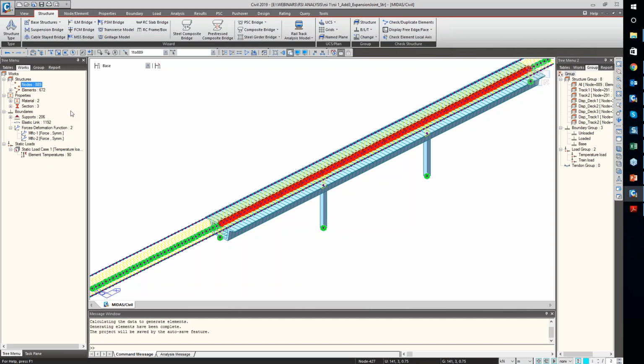Whatever design forces we are getting, we take an allowance of 5 to 10%, and we design the bridge, and then we check it for rail structure interaction. Because you can see here, we need everything about the bridge. We need the pier sections, we need the deck arrangement, and everything finalized, and on that we do this rail structure interaction check. So these derailment loads need to be considered during my design time.